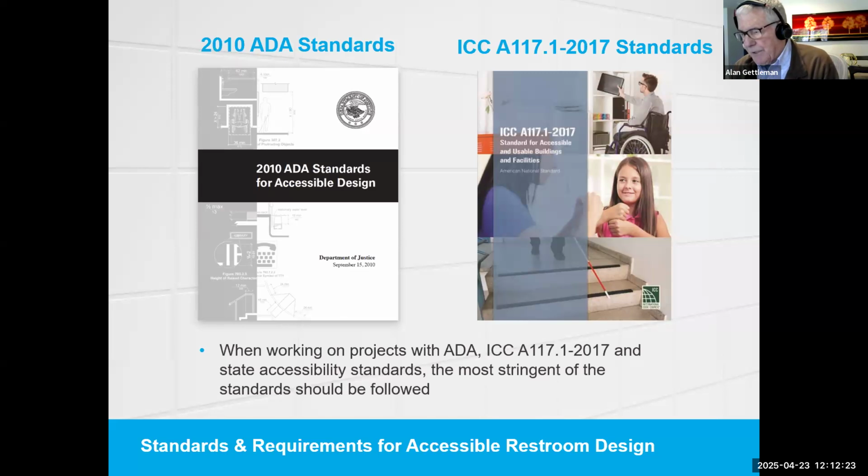At the bottom of the screen is our first takeaway alert. And it basically says that when you're working on a project that may have ADA requirements or A117 requirements or local, state, or provincial requirements, the best solution is follow the most stringent standard.